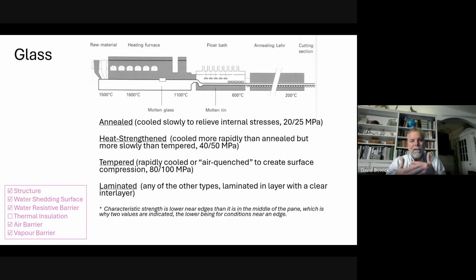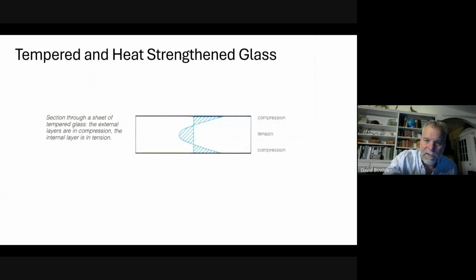But also, even if it's laminated so that it doesn't void the opening, the cracks propagate everywhere and you can't see, and that's also problematic. So we use laminated glass for the windshield so that it has the strength benefit of multiple layers, so that breakage doesn't pass through the laminated layer, so that it doesn't void the opening and you can continue to see, and it's safe enough to stop driving. So we use different types of glass in different situations in order to manage the hazard of breakage.